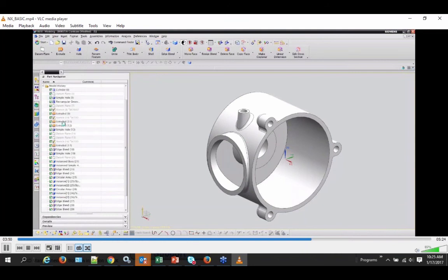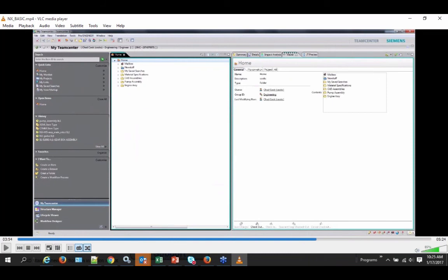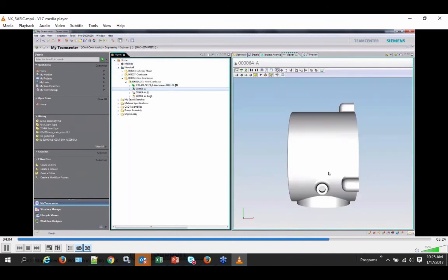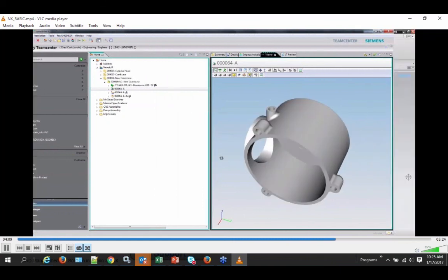And it is saying that I have to actually update the drawing too, and I'm doing that. So what I just did is I started from an existing part so that I'm not reinventing the wheel. Then I leveraged that existing design to create my new design with some minor changes and saved it as a new part. So that's what I did. Again, that new part got saved inside Teamcenter, right? Just like the previous case, a lightweight JT is also created, and obviously a drawing file is also created for that.